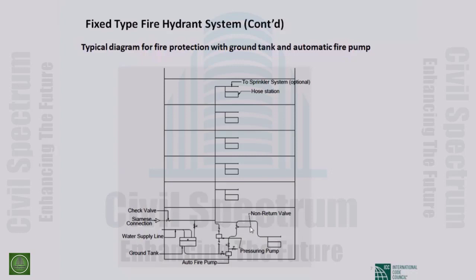In that case, in Dhaka city, particularly in Azimpur or in Fakirapul, there is a supply reservoir with water at a very high level. If it is directly connected with those types of systems, you may have sufficient pressure to spray. In that case you may not require a pressure pump, but it is not normal in Bangladesh. So in general, in almost all areas of Bangladesh, you should have a pressure pump.